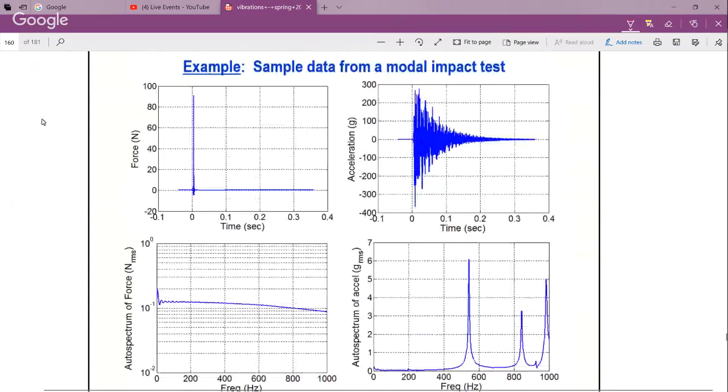This is just an example of data that I had loaded a long time ago, over a range of 0.5 of a second. You can see that the hammer pulse is quite narrow. You'd have to zoom in on it to actually see it. But I can clearly see I don't have a double hit, so I trust that data. That's the time trace for my hammer hit. It's about 90 newtons, so it's not a lot.